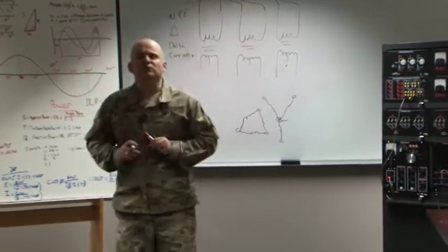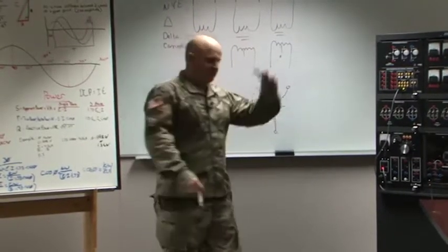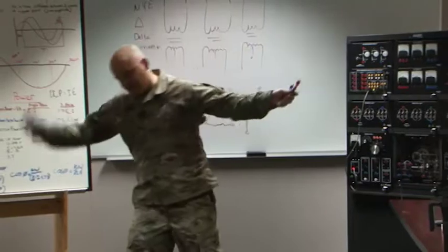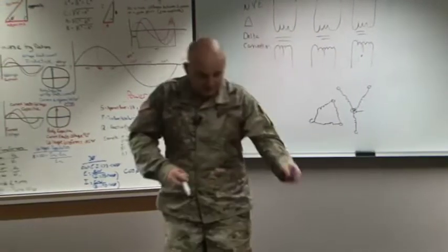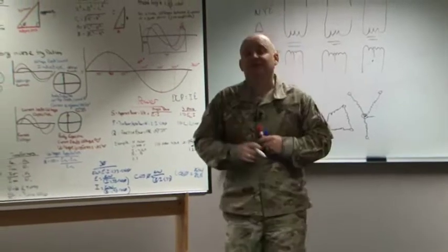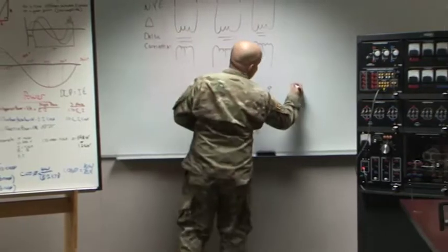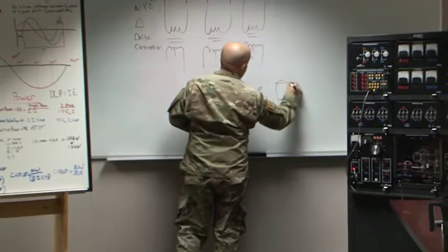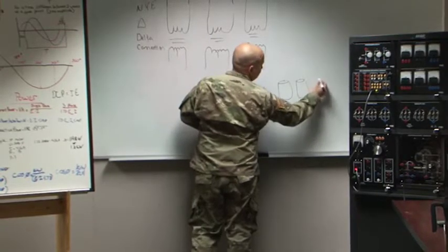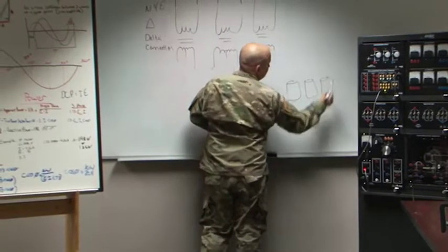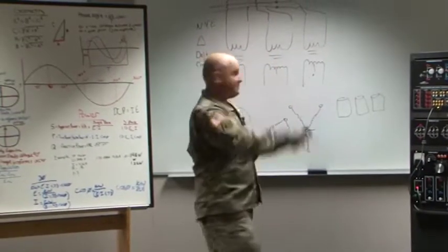So it'll say, well, if you have this voltage and you need this voltage, make this connection. If you have this voltage and you need this voltage, make this connection. All right, and it even goes into the specifics of where on the transformer, on these little single phase cans, because now you could look at this configuration right here, just like this. That's all that is. We got 3 single phase transformers, and you've probably seen that before too on that pole,